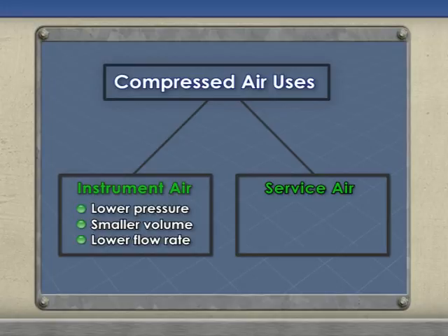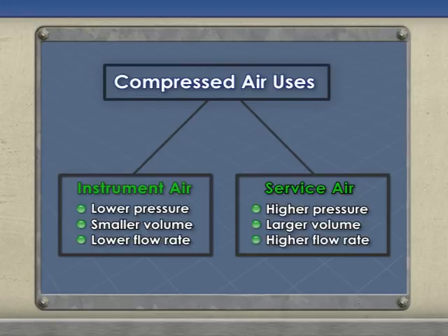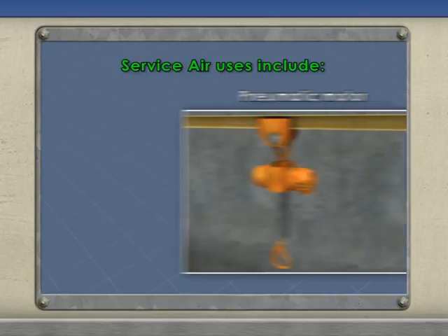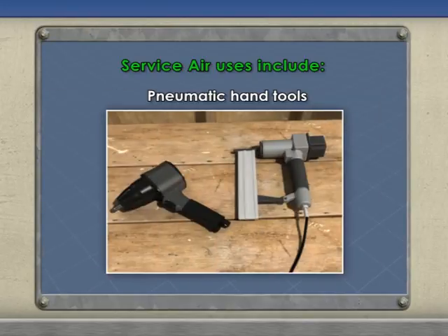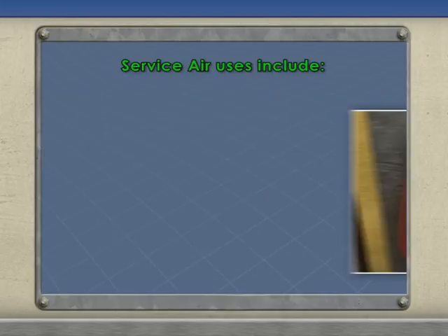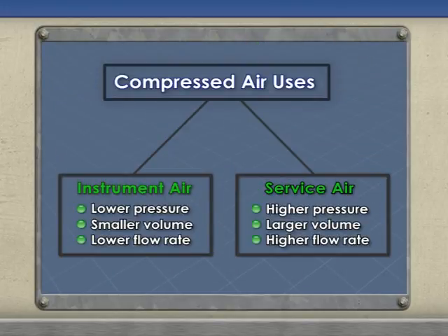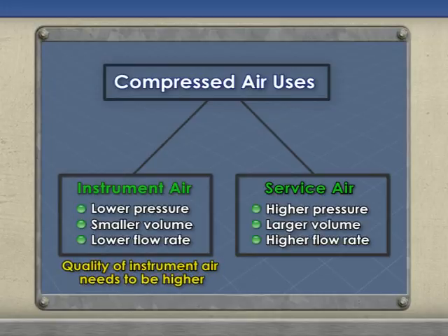Service applications usually involve the use of compressed air at increased pressures, larger volumes, and higher flow rates to perform work. Service air uses include pneumatic motors, pneumatic hand tools, and blow-down air hoses. Due primarily to the small size of the equipment used in instrument applications, the quality of instrument air needs to be higher than the air used for service applications.